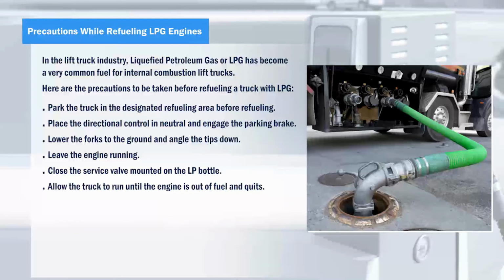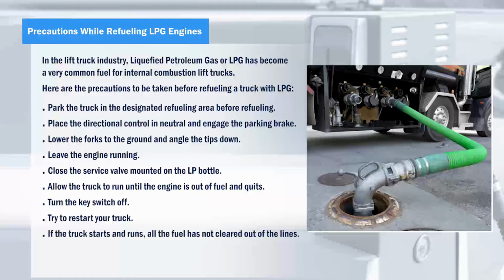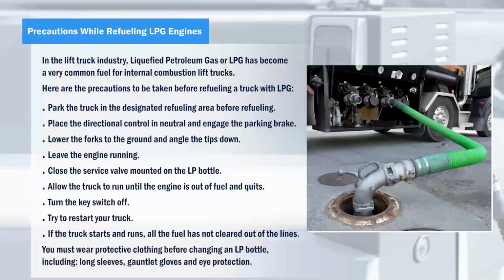Allow the truck to run until the engine is out of fuel and quits. Turn the key switch off. Try to restart your truck. If the truck starts and runs, all the fuel has not cleared out of the lines. You must wear protective clothing before changing an LP bottle, including long sleeves, gauntlet gloves, and eye protection.